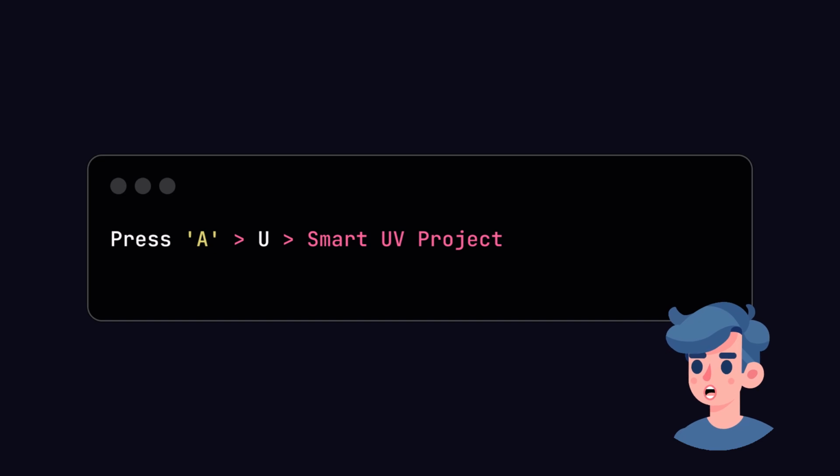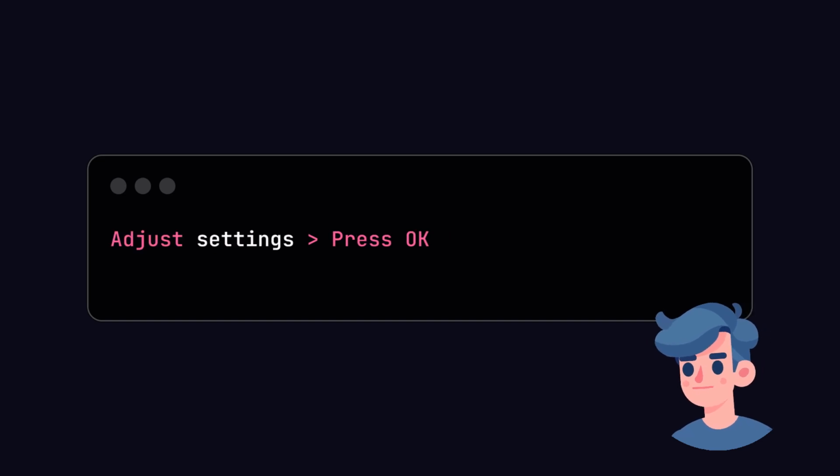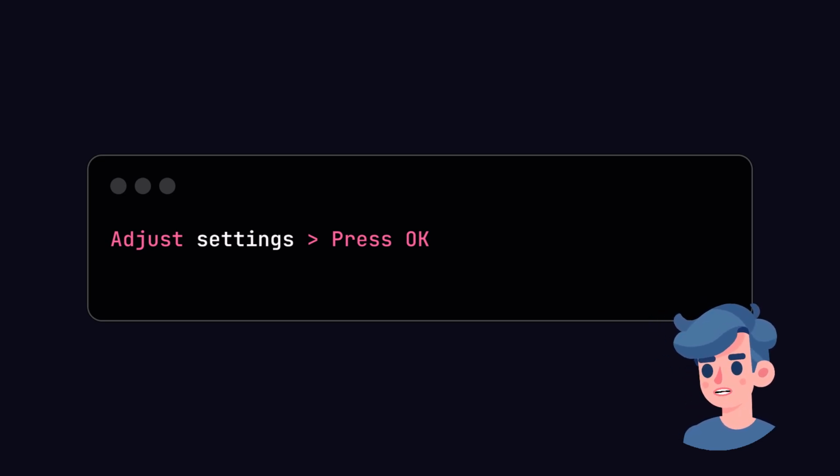Now, let's get a little more advanced and create UV maps for our model. Go back to Edit mode and press A to select all. Then, press U to unwrap the mesh and select Smart UV Project. In the window that pops up, you can adjust the settings for the unwrapping process. Keep the defaults for now and hit OK. You'll see how Blender lays out the UV islands. This is crucial for applying textures correctly.